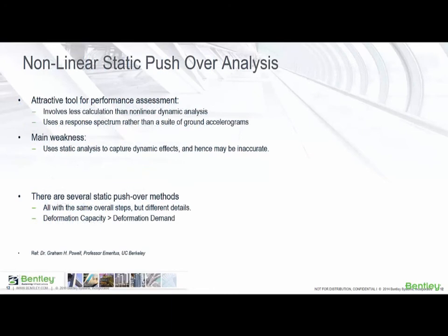Nonlinear static pushover analysis. Pushover analysis is an approximate alternative to nonlinear time history dynamic analysis. As discussed earlier, the time history method is complex, tedious, and time-consuming. Pushover analysis, on the other hand, involves fewer calculations. Pushover analysis also uses a single response spectrum as opposed to a suite of ground motions.